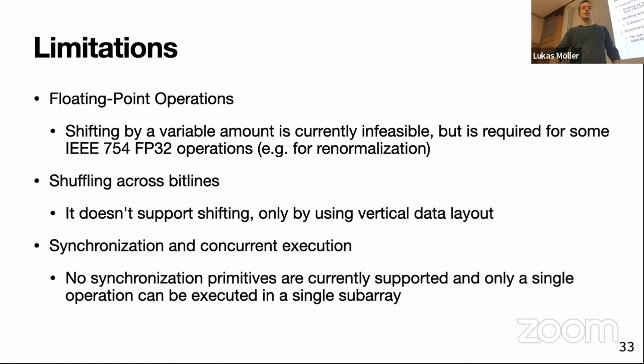And synchronization and concurrent execution is also limited right now because no synchronization primitives are implemented. Although we could, in theory, schedule multiple SIMDRAM programs at the same time to different subarrays. This would be supported by SIMDRAM, but without synchronization and concurrent execution, this isn't too useful.